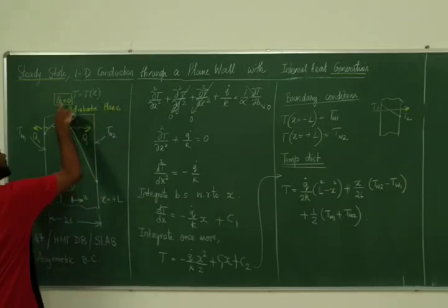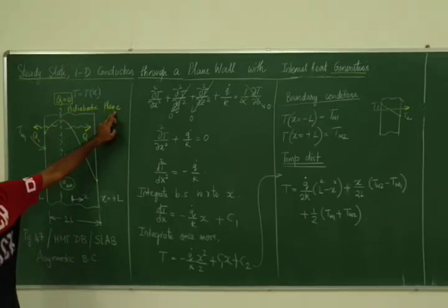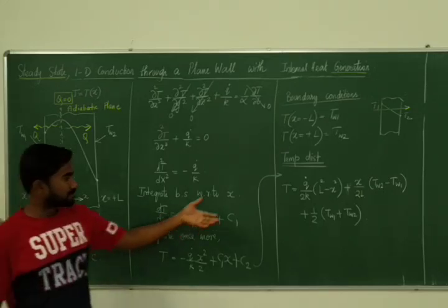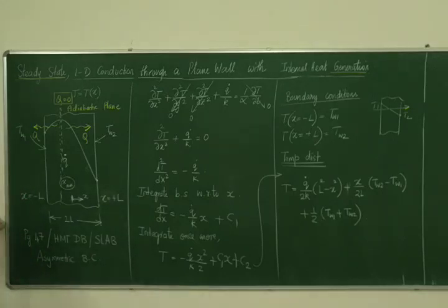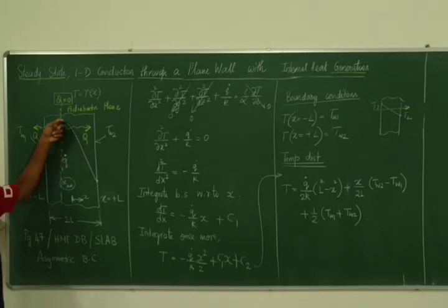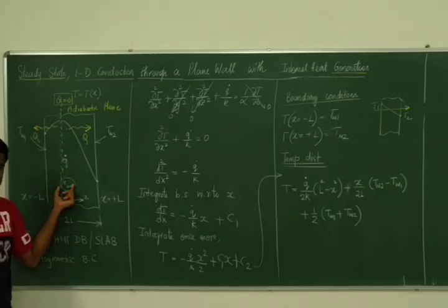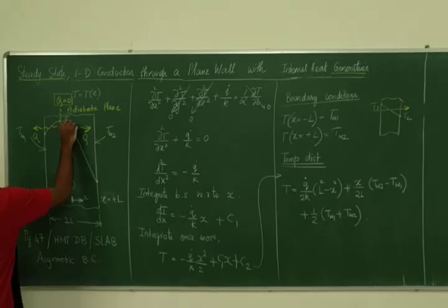You know, adiabatic means no heat transfer. So this plane on which there is maximum temperature is called an adiabatic plane. We will discuss all these when I derive the heat transfer. But beforehand, from the temperature distribution, you can tell a lot of things about heat transfer. One thing, I repeat again, the temperature distribution is quadratic. It has to reach a maximum somewhere in between. Where the temperature is the maximum, that's a very important plane. I'll call that x location as x max, and the maximum temperature I'll call T max.